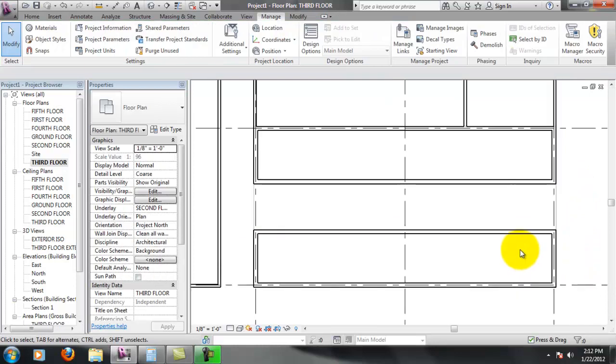Now, the recommended value for elevators in this orientation is 1.75, with 3 on this side, 3 on this side, with a corridor here. This is where you would wait for the elevator. It recommends that you multiply the depth of the elevator by 1.75, and that gives you the minimum out here.